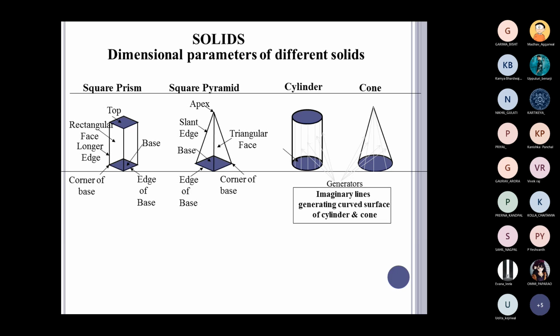In the case of a cylinder, to calculate the amount of material that will be consumed, we create lines in the vertical direction at multiples of the width. Then, when we open out that part, we can evaluate the amount of material required. There is one more thing.